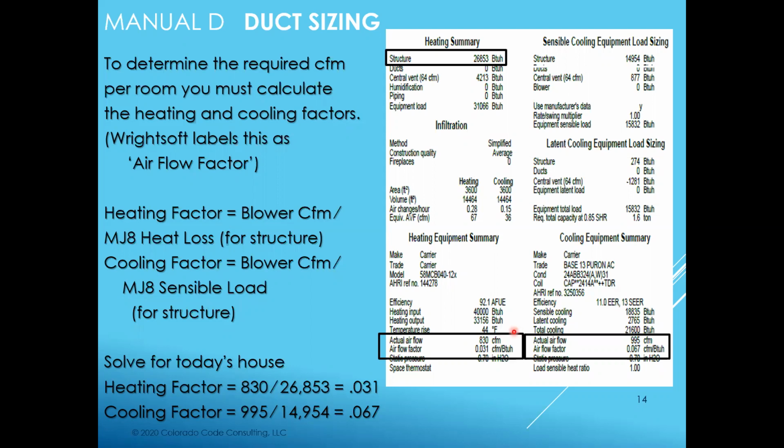Well, let's say you've got all this said and done and you had it all good. And then you get out in the field and say, gosh, it's running too hot. It's not moving this 830 CFM, because we also talked about how those fan speed charts are developed at sea level. And fans, the way they work, scoop in the air, and that doesn't work as well in altitude because the air is less dense. So it's not scooping as much air each time it moves around the circle there. So what we found in the field is we actually had to notch it up a speed or two.